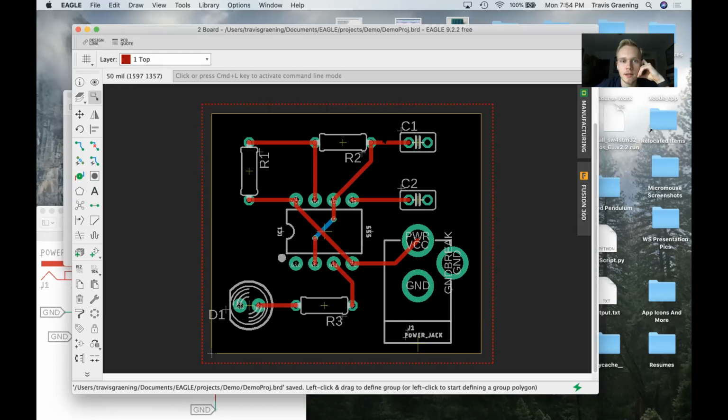So Jun is saying leave, yes, option clicking is a great way to do that. Otherwise, you're just going to be on the other grid. It kind of messed up the air wire. So, are you able to just Command Z or undo to get back to the state you were at before? That's the way I do it. I just Command Z until I don't have that air wire issue anymore.